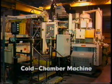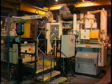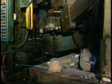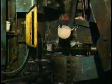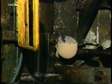The cold chamber machine is used primarily to die cast the higher temperature aluminum, magnesium, and copper alloys. In the cold chamber machine, the charge is supplied by ladle or feed system from an external furnace source. The plunger and metal transfer pipe are not submerged in the molten metal.